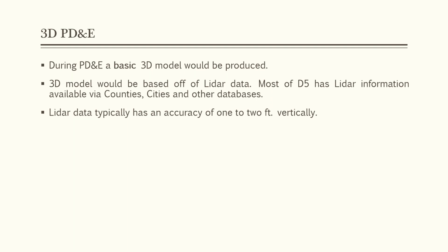And that Lidar data typically has an accuracy of 1 to 2 feet vertically, right? Now there's a lot of different data out there, and you can refine that, choose what data quality or accuracy that you want to utilize on your project. But it's typically somewhere around 1 to 2 feet vertically.